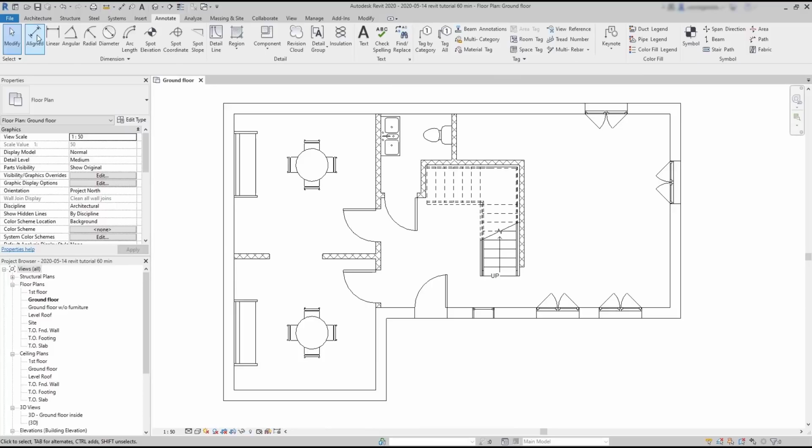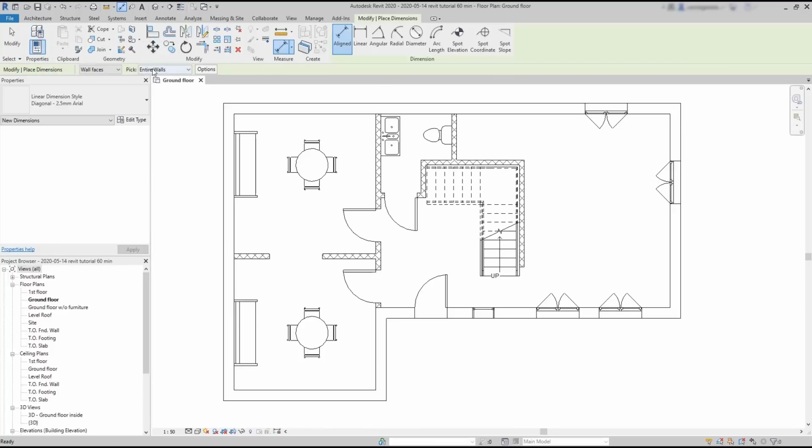In the next example, I'm going to create a dimension line, but this time using individual references. I pick these two reference lines. Then, to place just this dimension, I just click anywhere out of an individual reference. That's what I showed to you before. But let's repeat this.